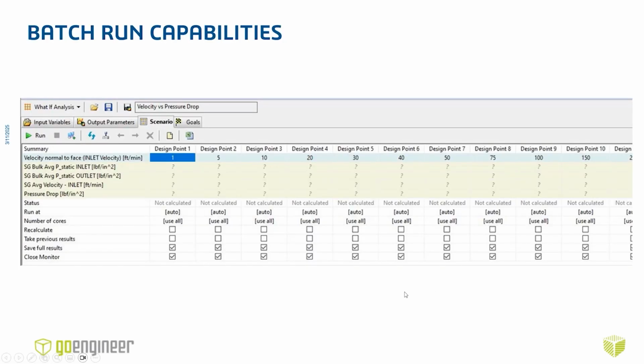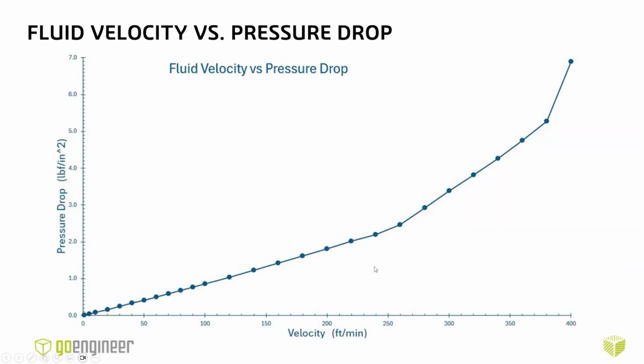Let me show you a little more what that means. In Flow Simulation and 3D Experience, there are methods of doing a batch run. What I would do is have a varying velocity at the inlet. So vary velocity from the lowest possible velocity that might be hitting those fins to the max possible velocity, and be measuring pressure drop from inlet to outlet. So across that bank of fins, I would create a curve something like this. As velocity fluctuates, pressure drop fluctuates. Great.